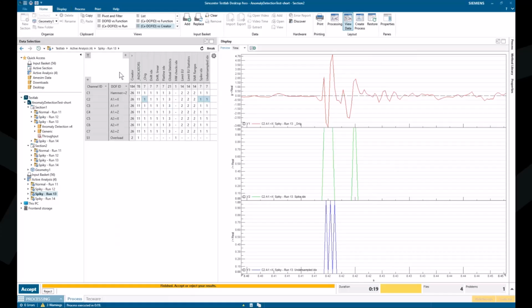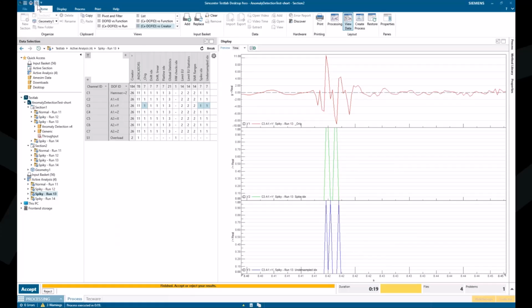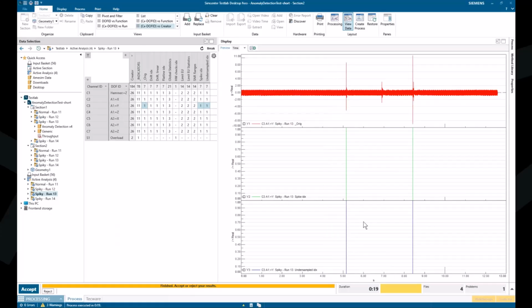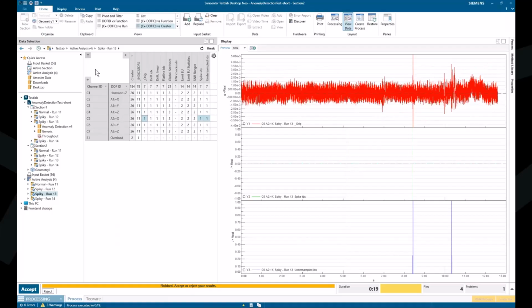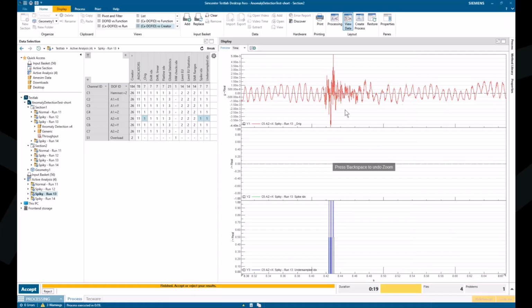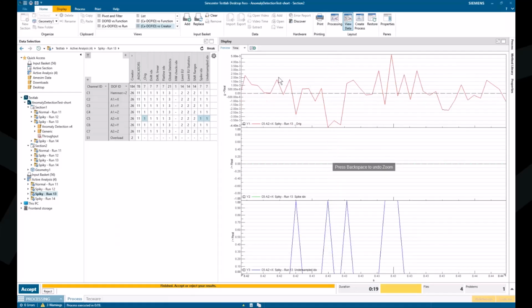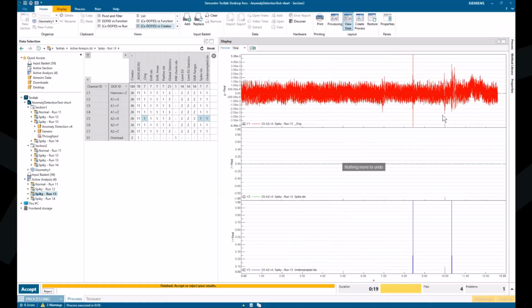And again, if you, for example, go to the next one, you also see this is still picking up on the same events here. Both are labeled spikes and undersampled. But if I continue to go to other channels, you will see that there are some channels where no spike detection has triggered, but the undersampling has triggered. So there are 2 places where we think it's undersampled, and it's something similar here. So that's really, these differences are larger than 40% of the full range. And then it's really questionable whether you have captured all the frequencies there. And the same here.